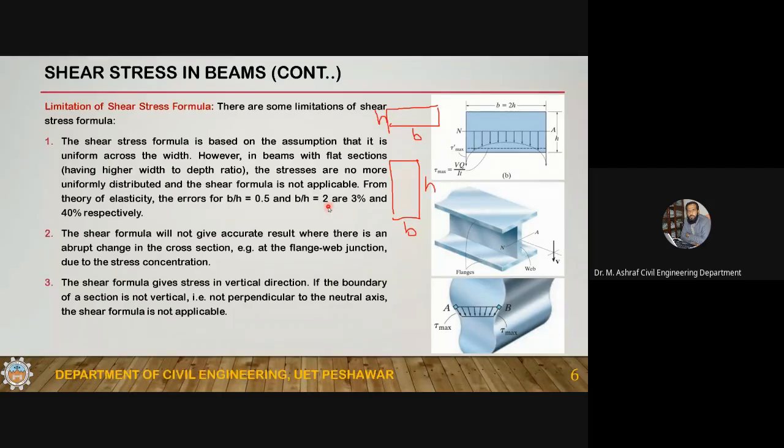So if you multiply 1.4 with 20, that will be 28 psi. The maximum stress, which is at the end, will be 28 psi, and the stress at the middle will be less than that. Since we are usually interested in the maximum value, it will be 1.4 times the value calculated using the shear stress formula.